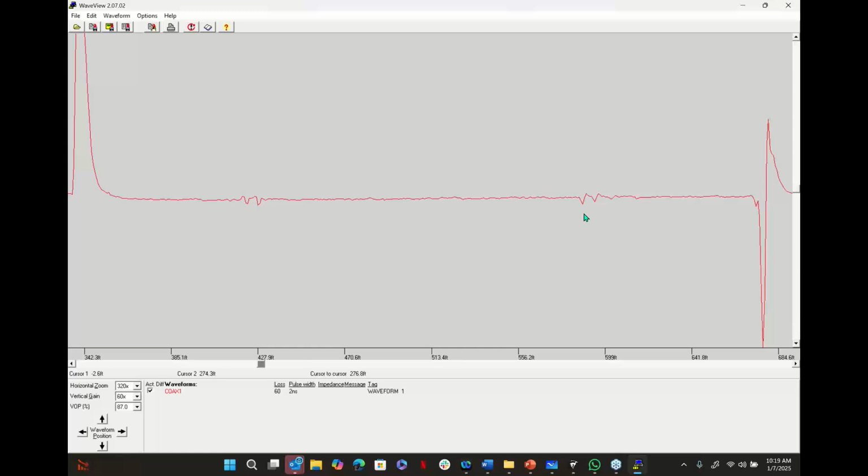You're probably not going to like my answer, so I'll just jump right into it and tell you. I'm going to say if you use a 50-foot jumper, at least 50 feet, sometimes a 75-foot jumper, and all of a sudden it quiets down your line, this still appears in the same spot, albeit 50 feet out, and then this one disappears. If that saves your butt and saves you from digging too many holes, you might want to consider that.